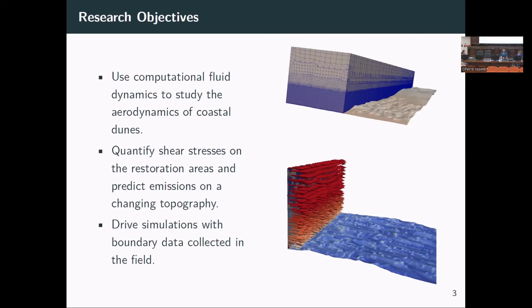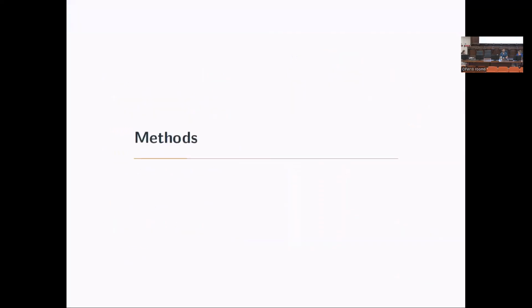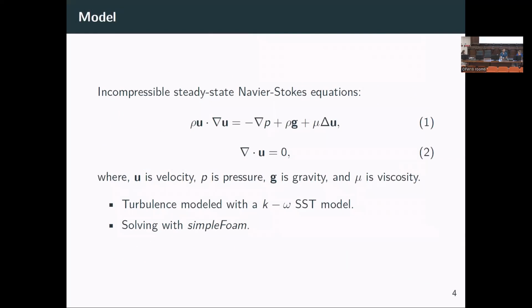This releases PM10. And of course, we're trying to drive these simulations with as much measured data as possible. A very classical setup, really similar to a wind tunnel: incompressible Navier-Stokes, steady state, k-omega SST turbulence model, and of course using simpleFoam.